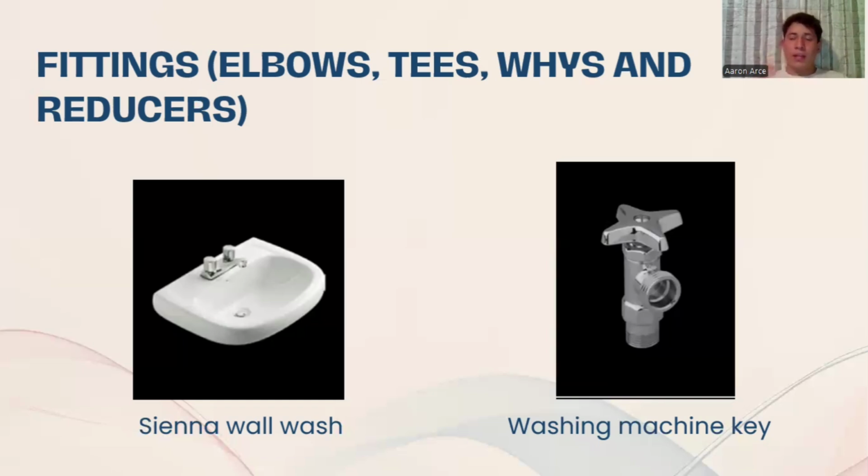The installation process is similar. Make sure the water source to the washer is turned off. This prevents water from flowing when connecting the hose. Check the condition of all the installation components. Place the gaskets over the water inlet hose connector where it connects to the washing machine or water supply. If you are removing the hose, turn the control counterclockwise to loosen the connection. Use feedback, handle pressure, or avoid damaging accessories.